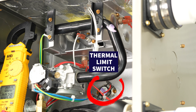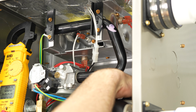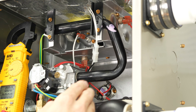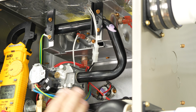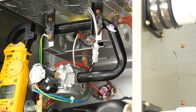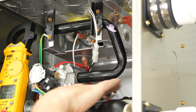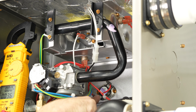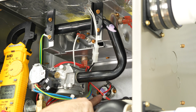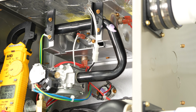Now back here, that is a thermal limit switch, and that will open up if the heat exchanger area back here warms up too much. So basically, if you have a low blower speed, that will be a problem. So if you either have a bad blower motor or a low blower speed, and eventually the heat exchanger just gets too hot back here, and that switch is going to open up the electrical circuit, and it's not going to have 24 volts down at the circuit board, and so that would be the issue.